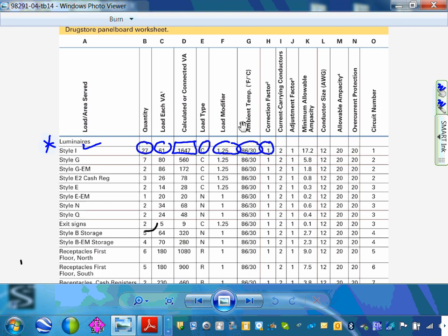So if the ambient temperature says, not 90, let's just say ambient temperature is 110. Do you guys remember that table? For 110, there's a derating factor. I can't remember which one of them, 310.15(B) something. Okay. So since the ambient temperature is not hot, do I need to worry about derating? No. No derating. Let's go to the next. Carrying conductors. Now, did you find it? So you're saying if it would be 110, it would be 0.87?